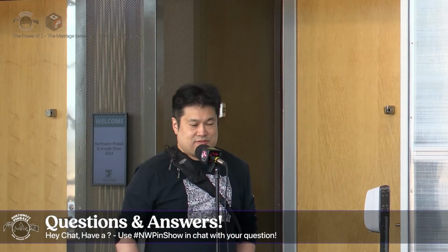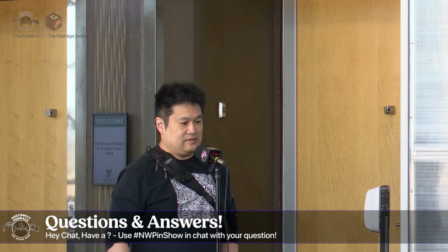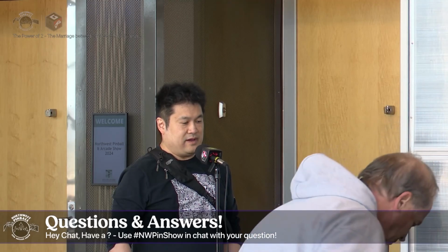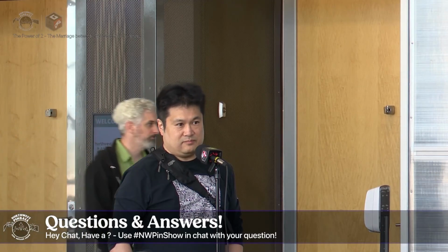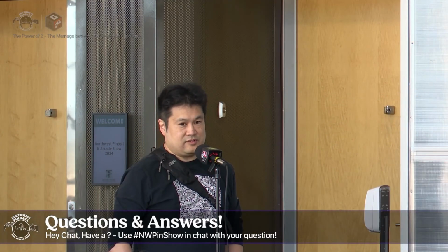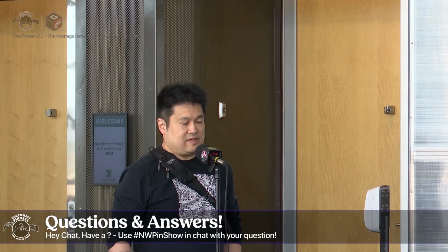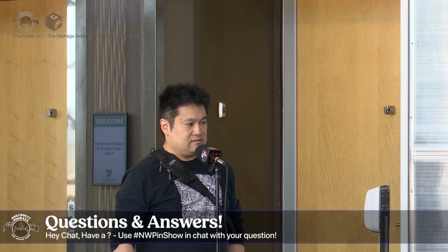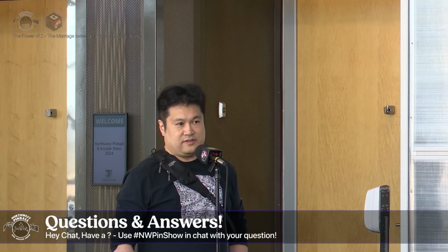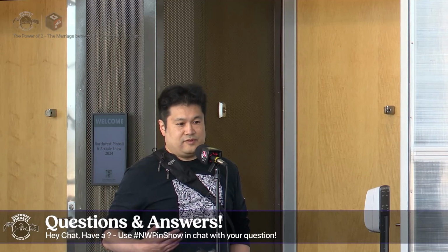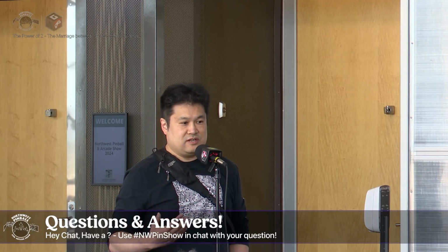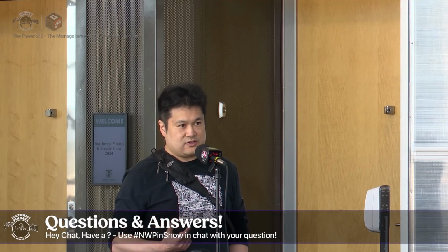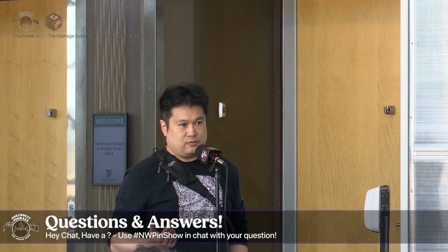Hi, Victor. So you touched on this briefly, but let's say you have a binary dump from an EEPROM, and sometimes you have to do a byte swap to change from little to big endian, or vice versa. That seems to be almost like the way the data is represented. Most significant, less significant byte seems to be from the reading software. So in terms of the endian representation, is that specific to the IC manufacturer, or is that the way the CPU would read it out and interpret the data?